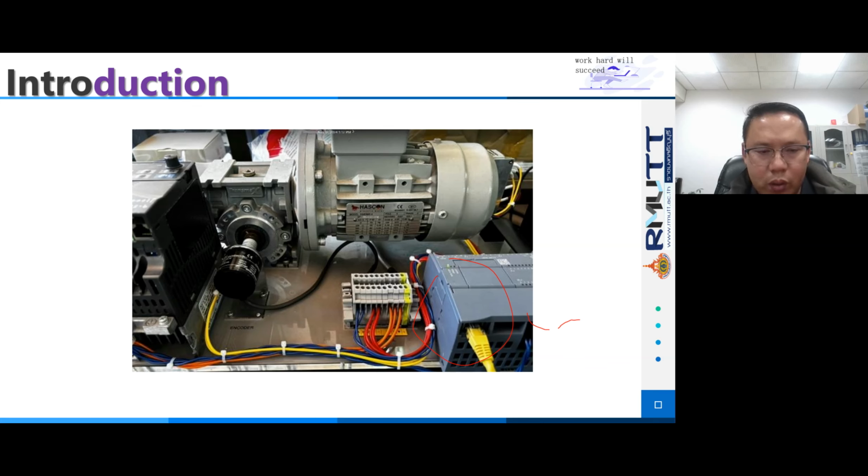In the figure, there is the PLC controller, the motor, usually a stepper motor, servo motor, or another controllable motor with position feedback, and the motor driver, which receives control signals from the PLC to drive the motor.